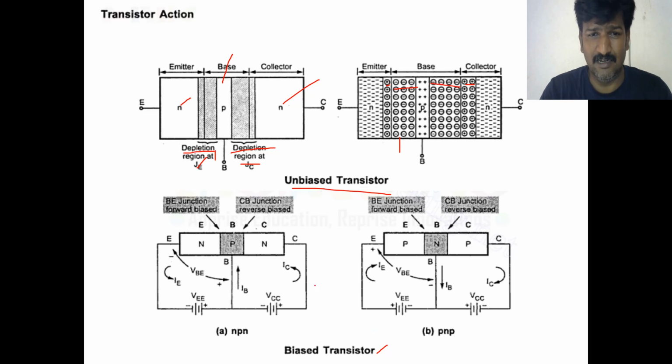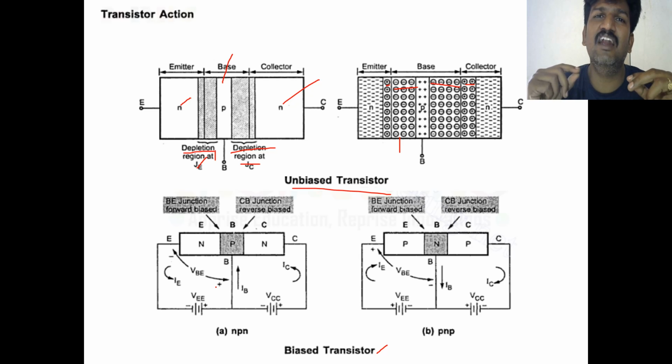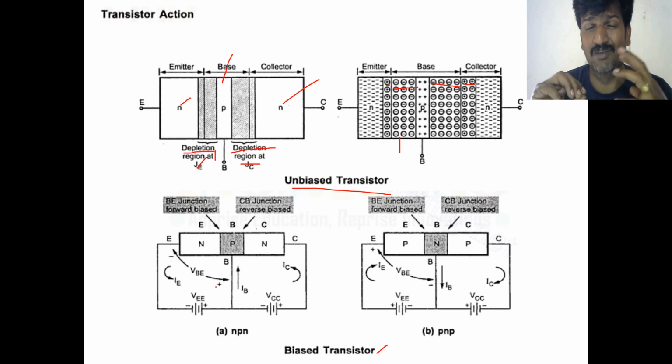Generally, you should understand this. Let me consider that a diode is going to conduct when you have positive polarity voltage at the p-type material and negative polarity voltage at the n-type material; then the diode becomes a conductor. If you interchange the polarity of the power supply, the diode will become reverse biased.